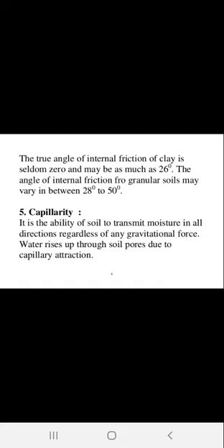It is usually considered that the value of the angle of internal friction is almost independent of the normal pressure, but varies with the degree of packing, right? For example, different particles have different shapes packed or overlapped together, but as the contact area is different between two particles, we can say there is a different angle of friction, right? The angle of friction in clay is 0 or maybe up to 26 degrees, and the angle of internal friction in granular soils may vary from 28 degrees to 50 degrees, right?